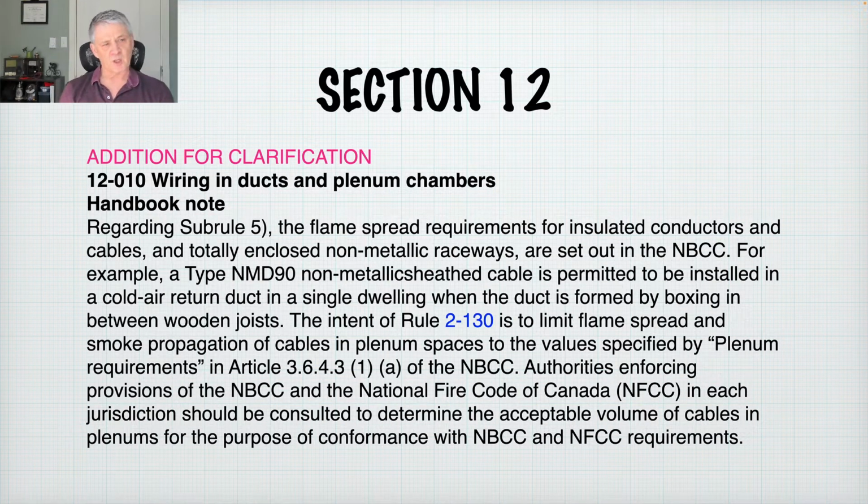So, addition for clarification, the wiring in ducts and plenum chambers. This is a handbook note. And we talked about the handbook a little bit at the beginning. We use the handbook regularly to help with rule interpretation. Regarding Subrule 5, the flame spread requirements for insulated conductors and cables and totally enclosed non-metallic raceways are set out in the National Building Code of Canada. In BC, we call it the BC Building Code.